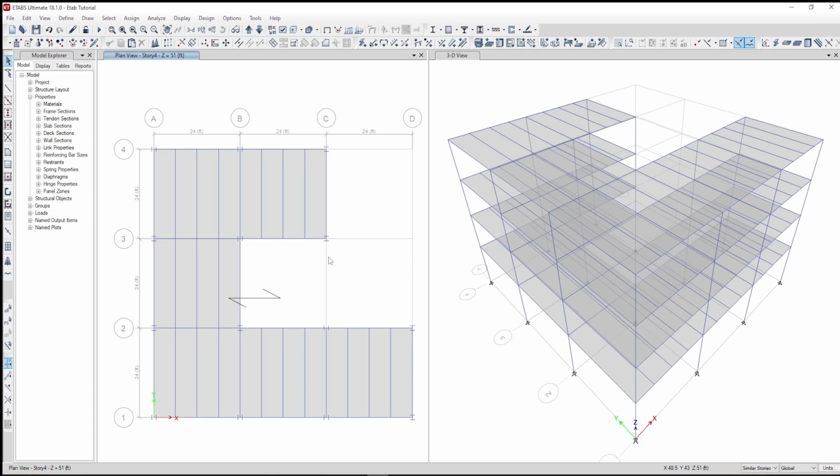Next, we'll add exterior cladding for wind load application. Exterior cladding consists of dummy shell objects that have no mass or stiffness. The areas will be used to apply wind load to the building. Use the Auto-Draw Cladding tool to create the walls.